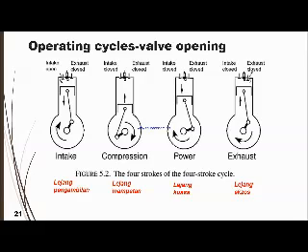First of all, you can see that this is not diesel, this is gasoline. We have a spark plug here. So when we have an intake stroke, one of the valves, which is for the fuel, will open, and then the piston will create a suction motion. Then the fuel will compress after the half cycle of the rotation, and compression happens when both valves are closed. When there is enough pressure, there is a timer set for the spark plug to inject the current and ignite the